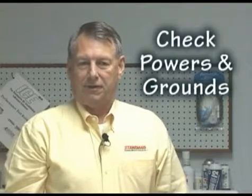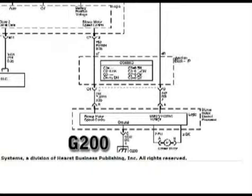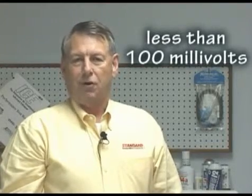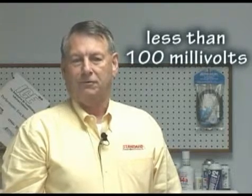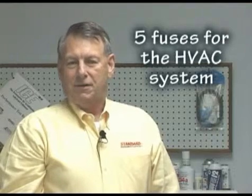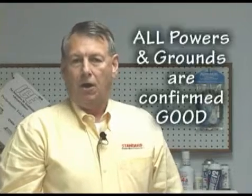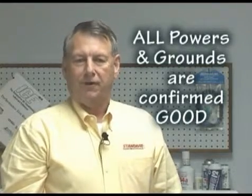Therefore, we will approach it from our traditional diagnostic standpoint. We will check power and ground circuits. Grounds are located at G200 and G203. Voltmeter testing verifies with the engine at idle that these grounds are less than 100 millivolts differential between the ground point and battery negative. On the power side, there are 5 fuses that supply power to the components within the automatic temp control system. All powers are confirmed and grounds are confirmed.